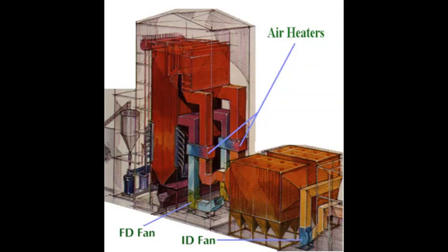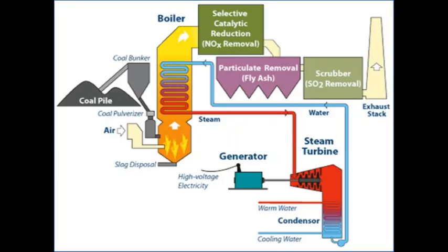If we cannot dry the coal, we cannot fly the coal. So drying is ensured, so that during pulverizing we are not getting paste, but we are getting dry dust of pulverized coal. And this hot air gives sufficient ignition temperature in the combustion chamber, that is the furnace, so that the fuel can quickly participate in the combustion process.